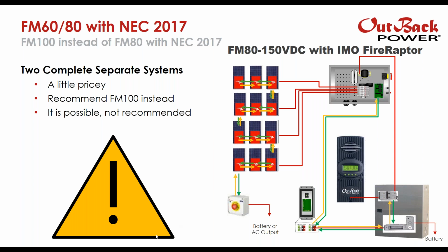All right, so the takeaway here is that we recommend the FM100 over the FM80 with NEC 2017 rapid shutdown. So we do it for reduced system costs, reduced complexity, and increased performance. So we do not recommend this. And I think I do have this information in the application note, although we don't recommend it. So we'll see if we'll keep it or not, but we highly recommend the FM100.